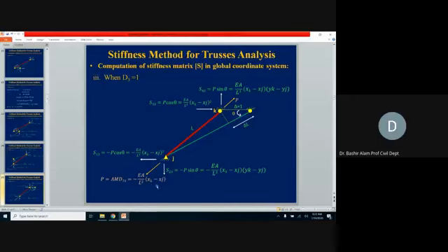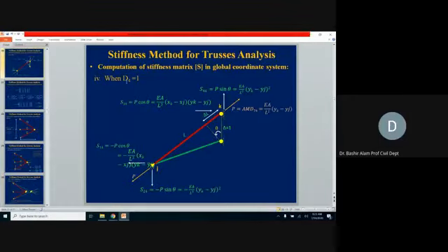Horizontal displacement was given. Similarly now, when we give D4 equal to 1, again if you see, from this green we are sliding it in the upward direction. So as a matter of fact, this should be red and this should be the new location we show with the help of the green line. Again, we see extension, because of the tensile force. This is how we fix the direction of this tensile force.